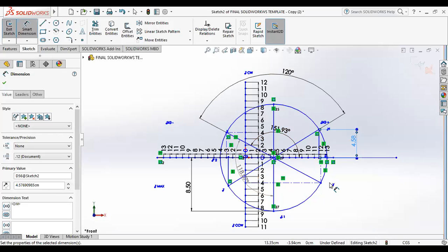From this I will draw a straight line, and then I will get point C. From this point C as the center, with XC or CY as the radius, draw a circle. This circle is called the Mohr circle. Wherever this Mohr circle intersects the horizontal line, there is no shear stress. This point is P1 and this point is P2. Whichever is the maximum is called P1 and the minimum is called P2. If there is minus 300 and minus 200, minus 200 is P1, minus 300 is P2. Sigma P1 and sigma P2.